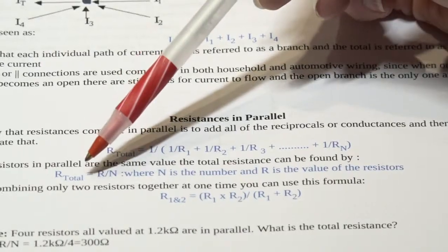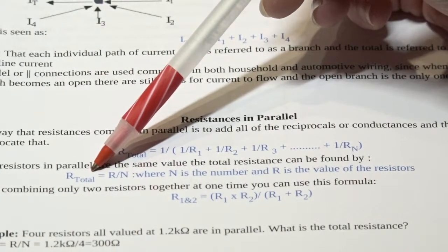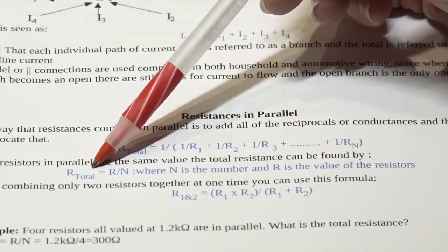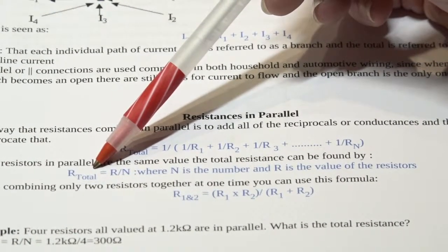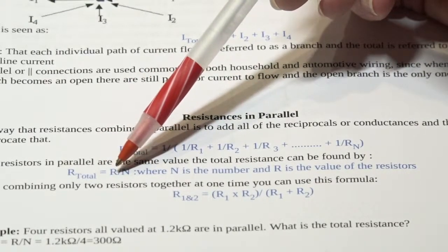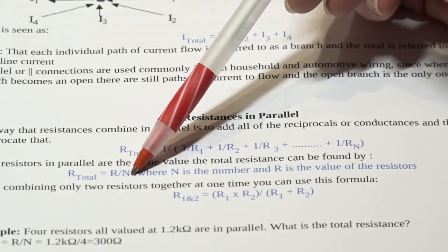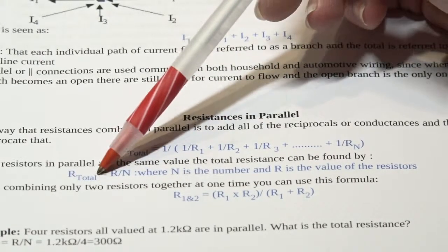Now, when it comes to total resistance, if you have several like resistors in parallel, you can simply take the value that they are and divide it by how many there are, and that will be the total resistance seen